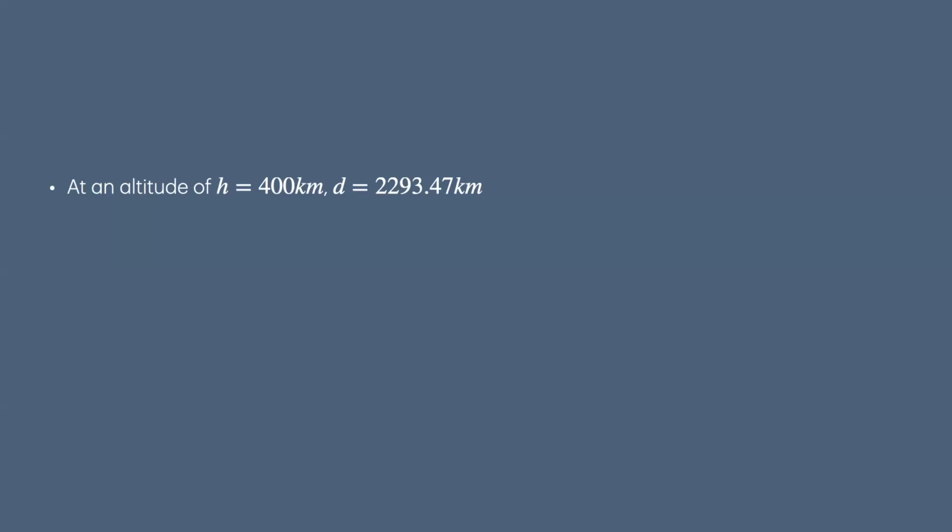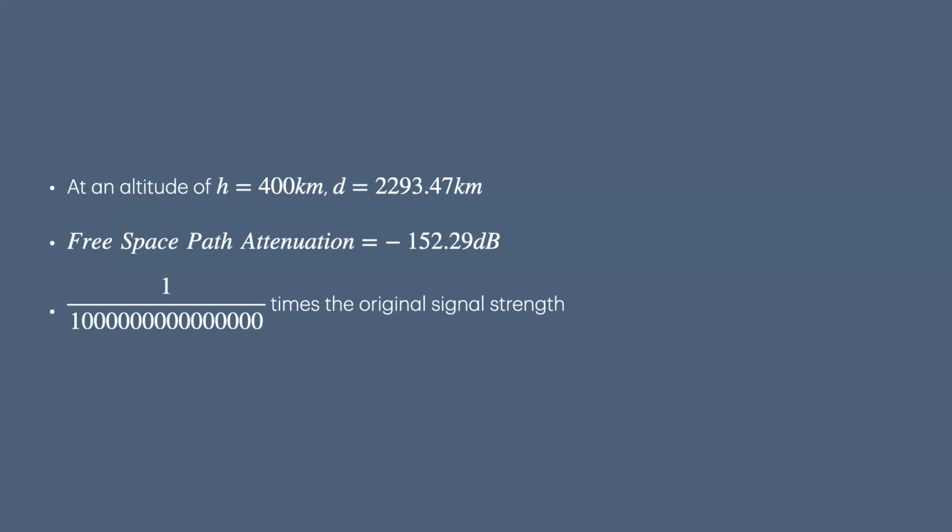And you lose a lot of signal in that distance. If you plug it into that equation, the free space path loss is a little under 153 decibels. How much less is that? It's that many times less. It's 1,000 million times less. And yet we hear it easily.